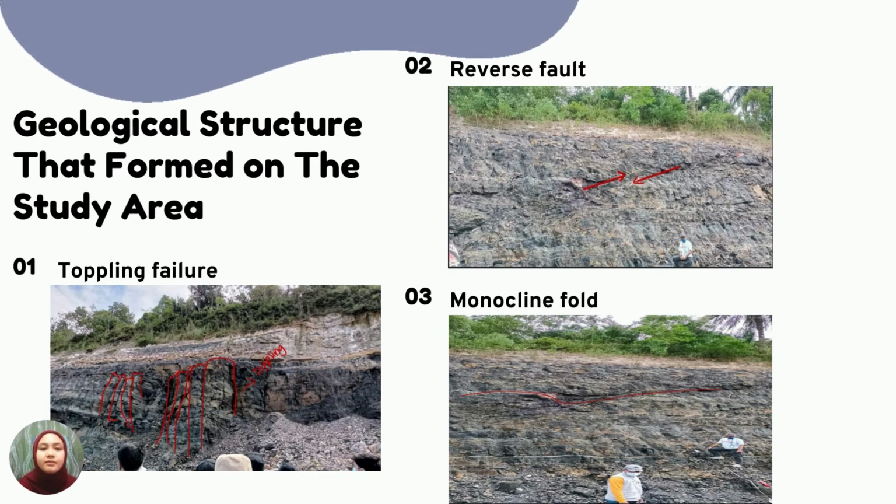The next one is the monocline. What do we know about monocline? A monocline is a fold consisting of two horizontal limbs connected by a shorter inclined limb. Monocline is characteristic of regions in which sedimentary rocks have been deformed by deep slip movement along vertical or steeply dipping faults in the older and deeper rocks. Most monoclines are classified as drape folds or fault-propagation folds because the sedimentary rocks are draped and folded as a result of movement along underlying faults.